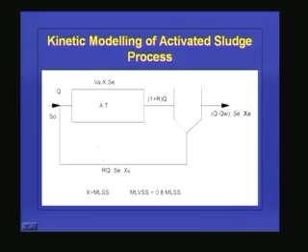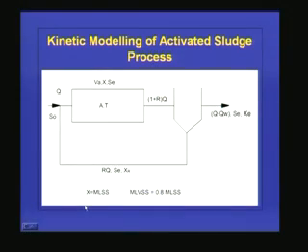And always we use this X to represent MLSS. MLSS is nothing but mixed liquid suspended solids. So, if you have that mixed liquid, and you find out the suspended solid concentration in that liquid, that is known as MLSS. So, we assume that mainly that is biomass, or another term is there, that is MLVSS, mixed liquid volatile suspended